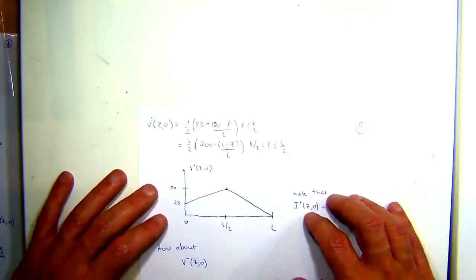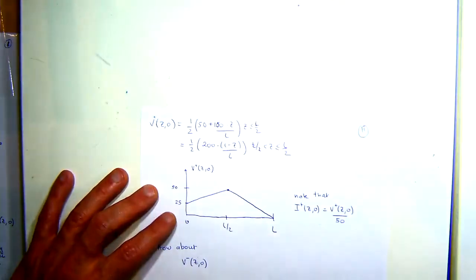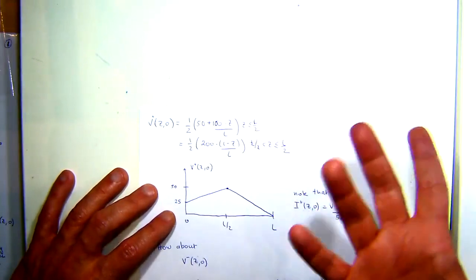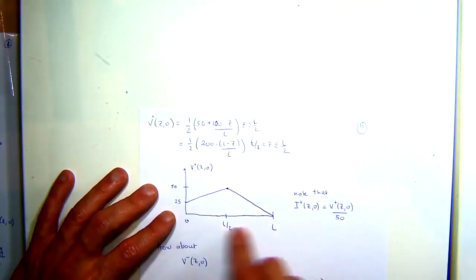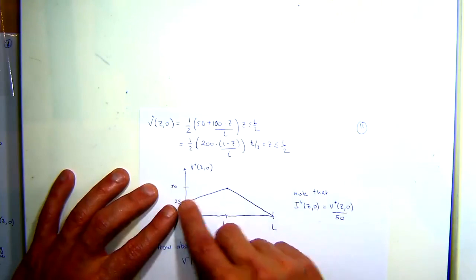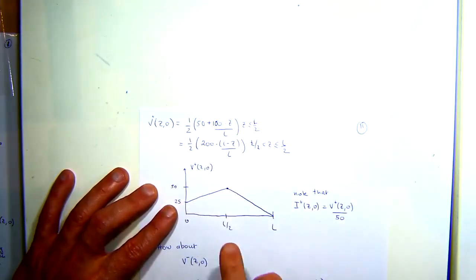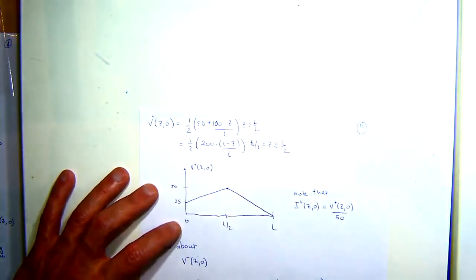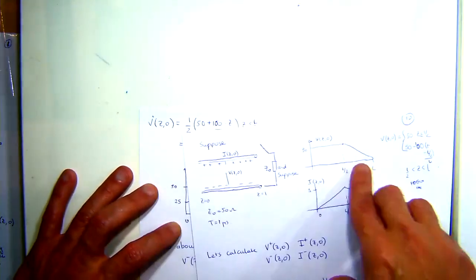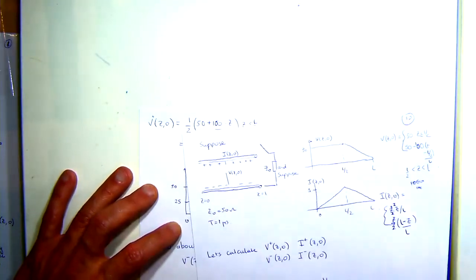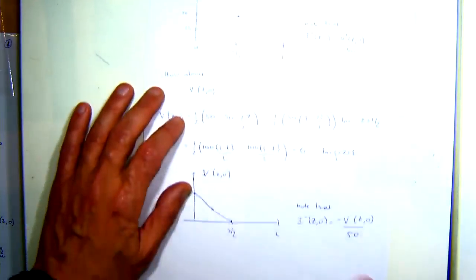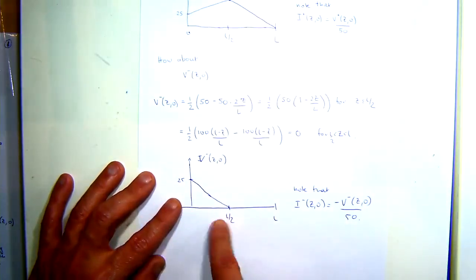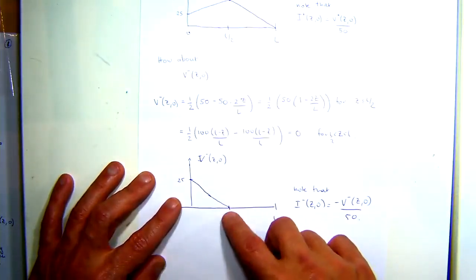And essentially all I did here was to say, well, for that particular voltage characteristic that I had, the positive going voltage on the line from 0 to L on 2 starts at 25, goes to 50, and then from L on 2 to L, it has this relation, goes from 50 to 0, based on this initial distribution of the total voltage. Right? And I also said that the negative going voltage is this. I calculated it, I shouldn't say I said that it was this. Okay.